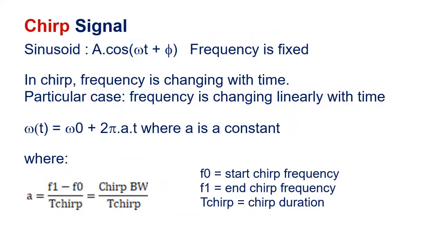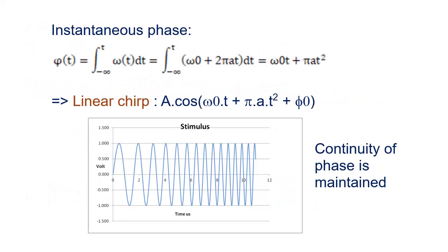Now we discuss chirp signals, used in communication and radar. It is usually a sinusoid-like signal, but frequency is changing with time. We consider a subclass called linear chirp, where frequency is changing with time linearly. For linear chirp, the time domain expression is derived and waveform plotted. You can visualize how the frequency is changing with time while maintaining continuity in phase.